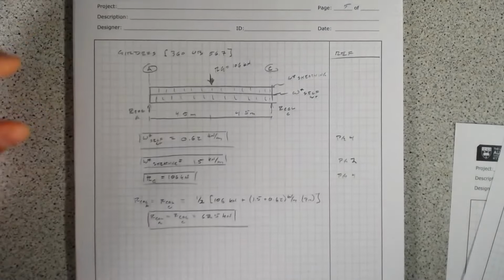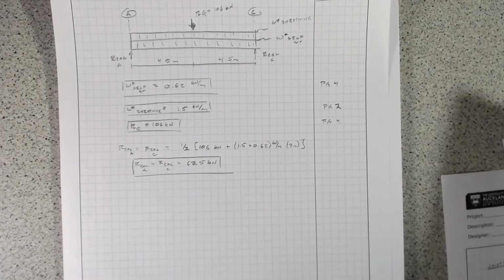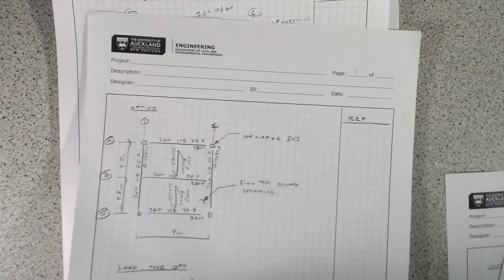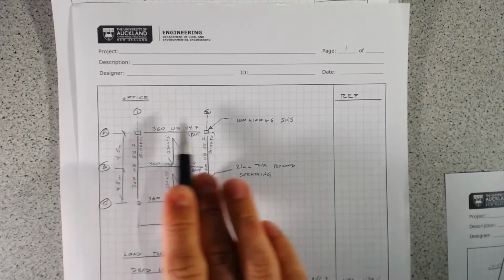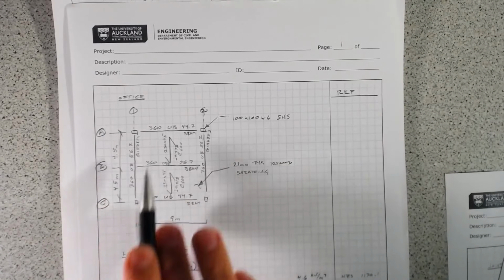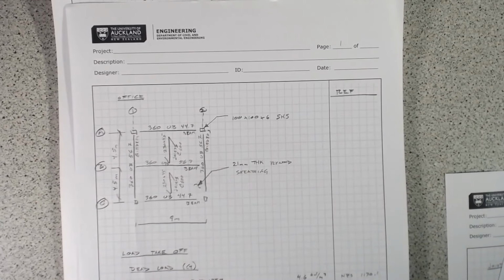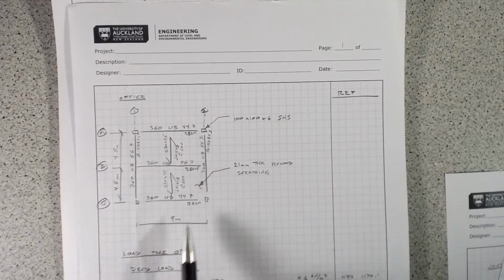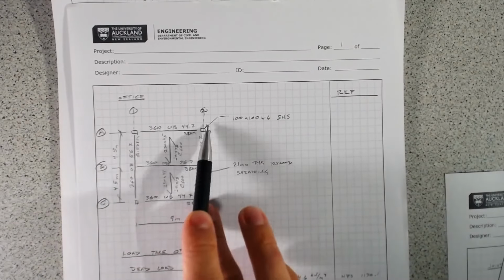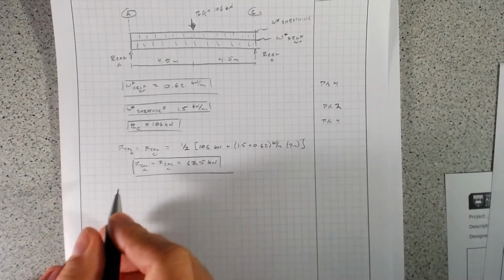All right, the final thing that we need to look at are the columns. So because we have a symmetric system here, where we don't have any openings, the framing's the same, we're the same dimensions in each way. That means that each of these columns will take essentially 1/4 of the load. And because of that, we only have to do one calculation, and we know the loads on all of the columns.